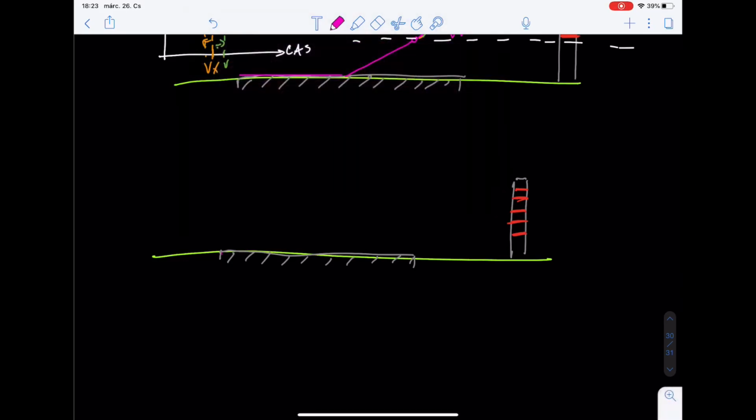So initially I take off, I have liftoff, I reach my screen height, and this is where it all begins. Let's presume that my initial flight path was maintained with Vx. So from this point, I fly with the best angle, and let's say I fly for T amount of time with Vx, and this is the point where I get to from the top of the screen height.